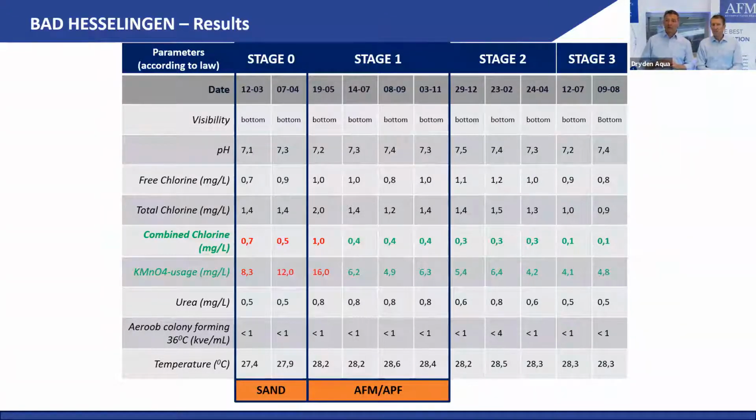So 2 hours later, they called me and said, Dominic, you were right. And honestly, I really love to be right. Because in the first backwash, the pool operator lost a little bit of media, which is good for us and for him. And therefore he said, okay, only backwash with 1 pump, and even this pump he closed down. So we had a backwash velocity of 20 meters per hour with the old AFM. It didn't do anything. That was not moving, and that's why the values were good the first week, and then they dropped. They changed the backwash regime back to the 2 backwash pumps, backwash at 45 meters per hour, and then you see the values were all good.